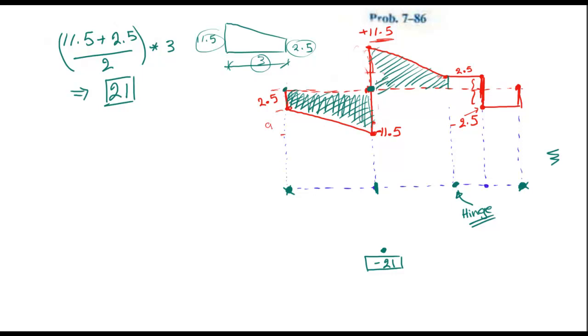shear and moment diagram. Or shear, I'm sorry, it's the area of the shear diagram here, plus, it's a positive, and we shouldn't forget to add it to the previous area. We don't just calculate it and plug in the number. We should add it to this area, because the moment at any point is the summation of the areas from the beginning until the point you are interested in. Okay, if we calculate these areas, let's draw it here.